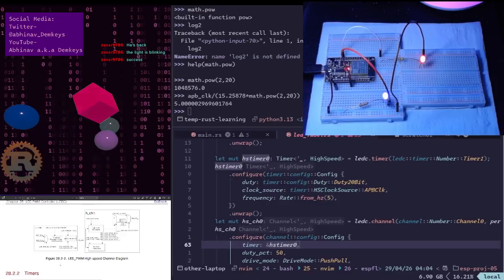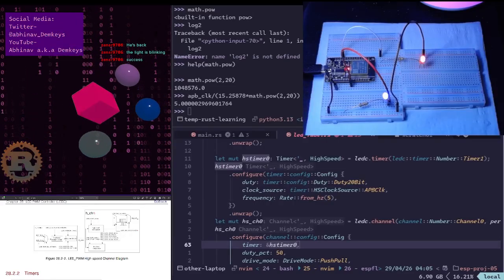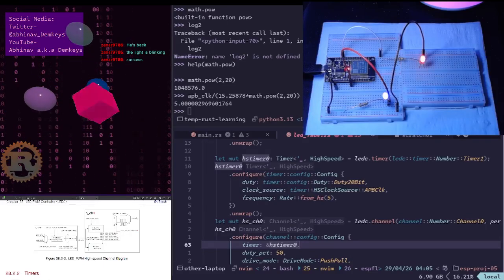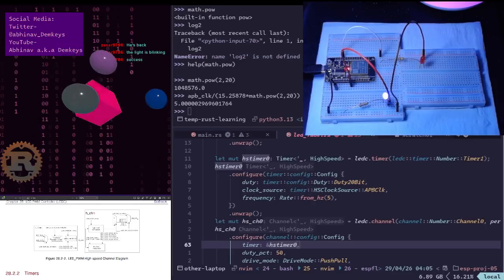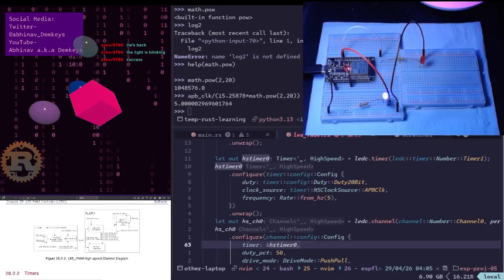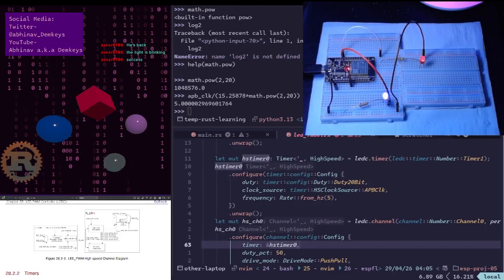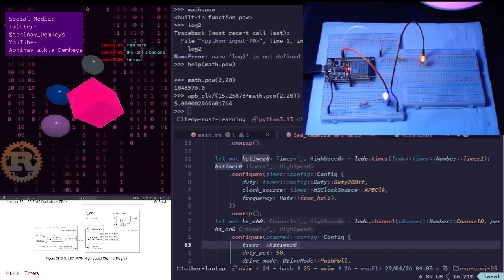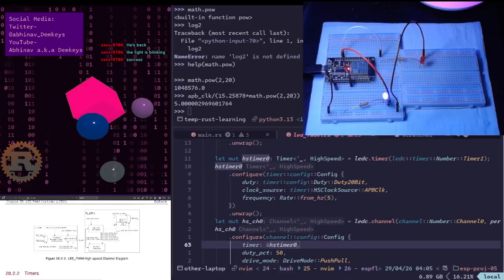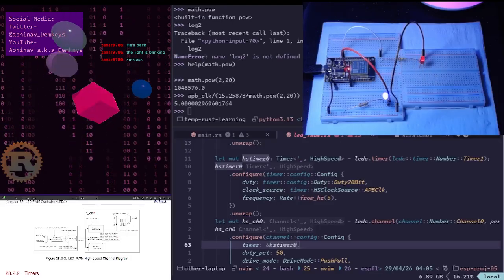At some point later, I'll have to look into how to set up a ref tick clock source. For now, we only have APB clock as our clock source, which means we're going to assume 80 megahertz the entire time, right? That signal gets fed into the fractional divider, and from the fractional divider, our signal is getting fed into the counter, right? But in the fractional divider, I need to look into how exactly things are working because